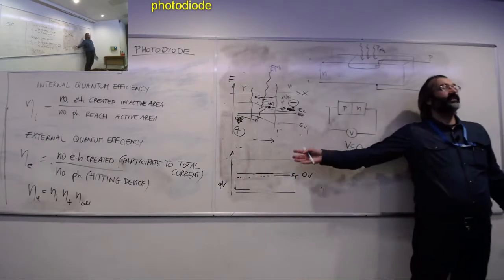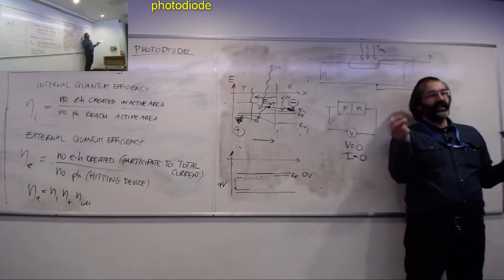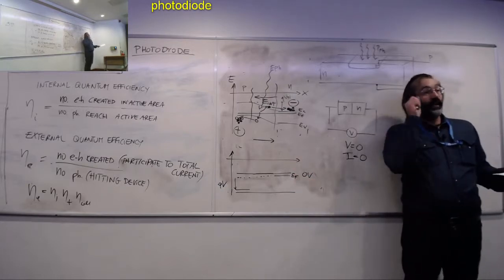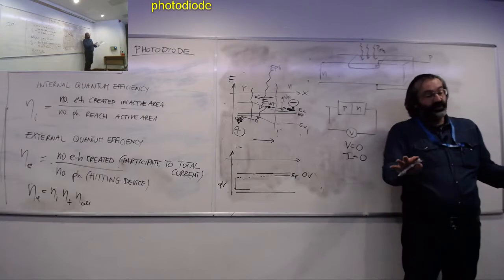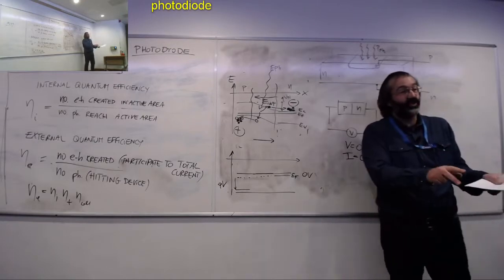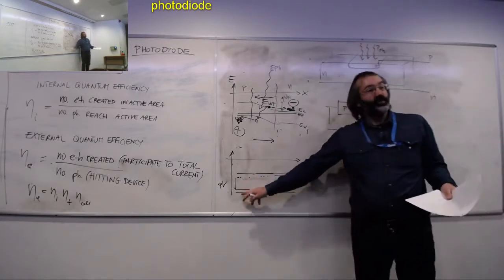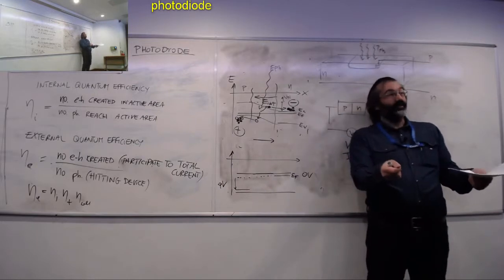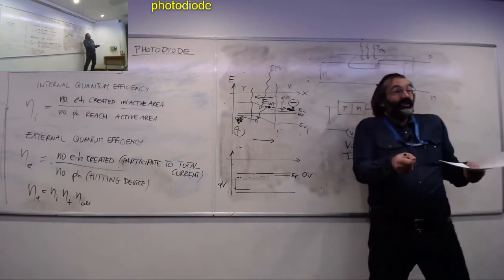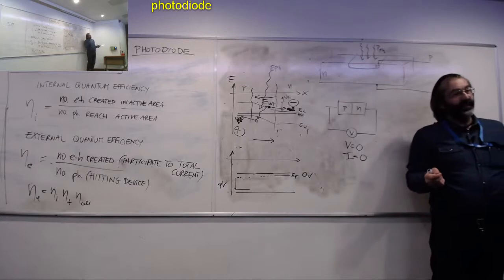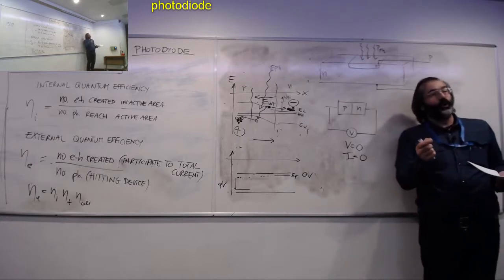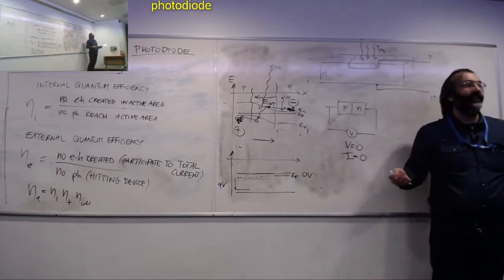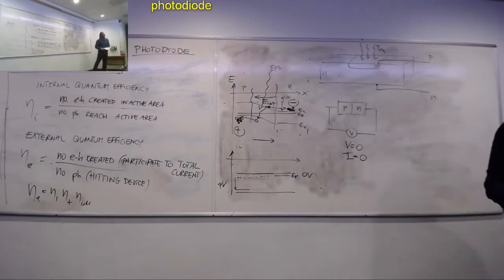So this voltage we've discovered. What we discovered right now is that if I take a photodiode, a p-n junction, and you shine light, the junction is not connected to anything, you just shine light, you will generate a voltage at the two ends of it. Because the junction is not connected to anything, this voltage has a name. It's called open circuit voltage. Very, very original.